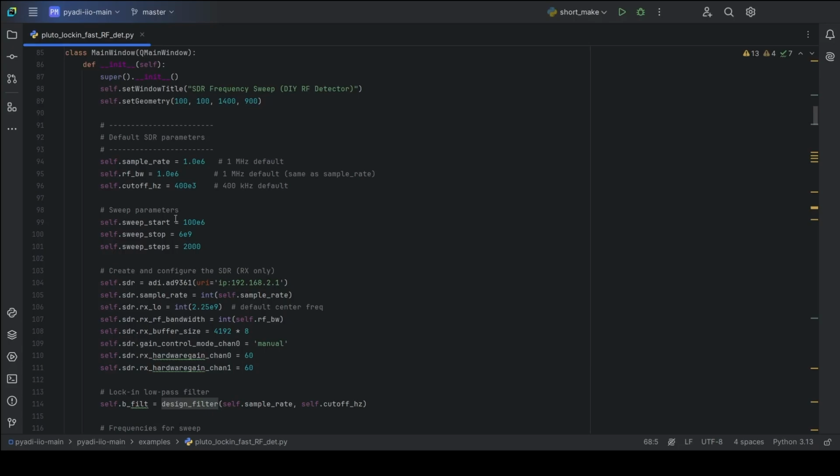If you want to, for instance, capture frequency differences within 100 kilohertz, you need the low pass filter cutoff frequency to be at least one decade below that resolution. Usually in spectrum analyzers, these resolutions can be changed in the device as well as the sweep frequencies. But it definitely means that as you increase the resolution and make the accuracy better, your sweep time increases.